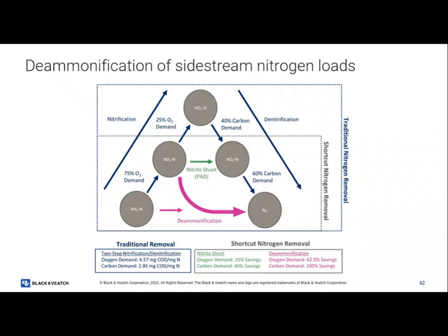So you should sample to inform what you're operating at. I don't mean that you shouldn't sample, Paul. Depending on what you're trying to do, you should be sampling to inform your operations. But in terms of taking a nitrite sample every day or a process troubleshooting one, use indicators and trends as much as you can. You're always going to be measuring TSS. We're always going to be taking ammonium samples. We're always going to be doing some of these things to make sure we're monitoring our process. But you don't need to do some of them as frequently as possible. You don't need to have it be busy work. Watch those trends and inform where you're sampling and why you're sampling for it.